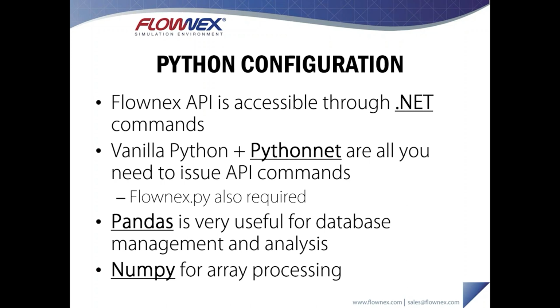That's basically all you need to start working with the Flownex API. We have created a flownex.py file. If you look in the help tab of your Flownex install, there is a Python button. This flownex.py file sits inside of that folder along with a simple example.